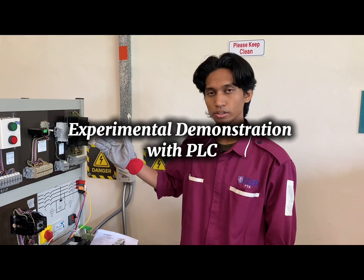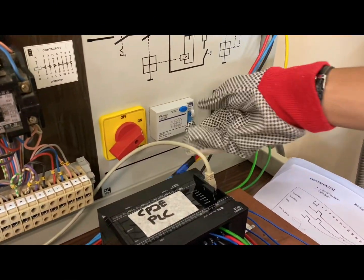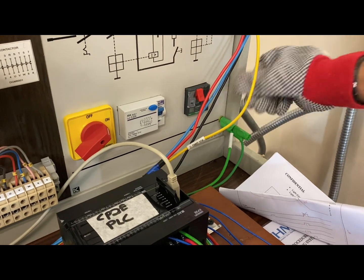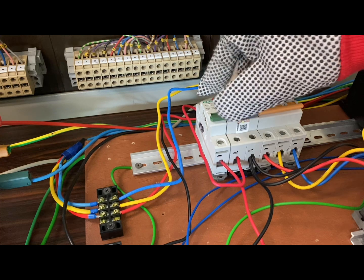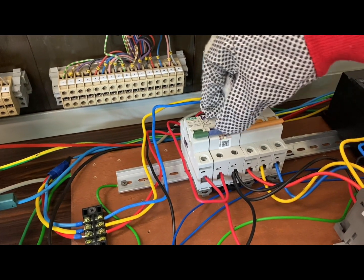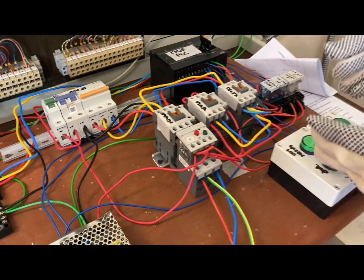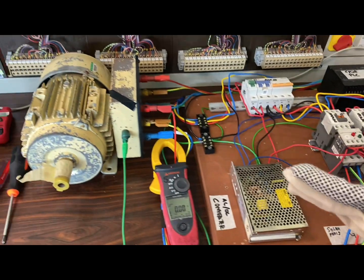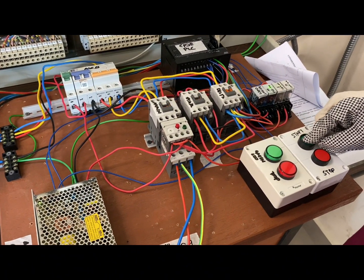So first I will switch on the MCB. I will turn it on. And then I will turn on the single pole and two pole MCB before I turn on the three pole, because I want to test the circuit first before I run the motor. So first we push the start button.